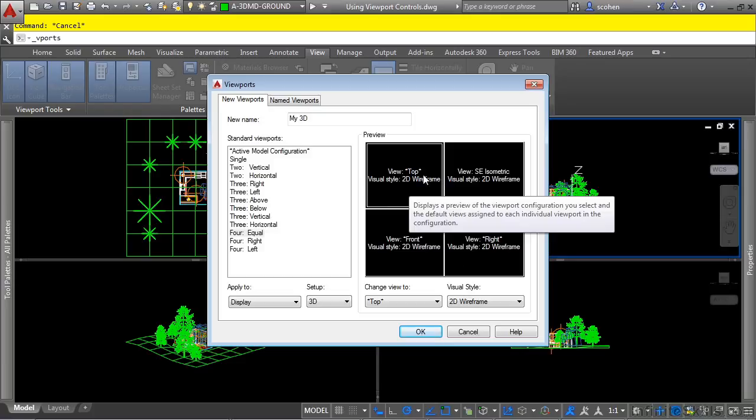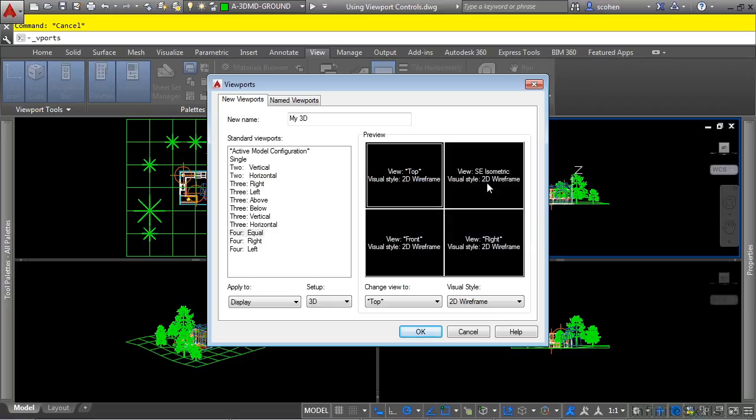So don't forget, this functionality, although we're showing it in 3D, can also be leveraged in 2D. For instance, a good example is, let's say you have a really large project and you want to copy a standard set of blocks from one area of your drawing along the project. You could have 2 viewports open, and the one viewport could actually be displaying your blocks, and the other viewport could be your active viewport where you pan around to copy in the different blocks.